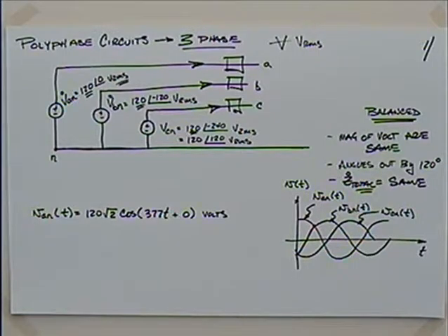If you want to change the phase on a voltage, you could do that with a capacitor or inductor. A lot of times we do it in a practical sense with a capacitor. A lot of motors will have a capacitor. There'll be capacitor start or capacitor run, where you put a capacitor in to shift the signal so that you can get more torque out of it.